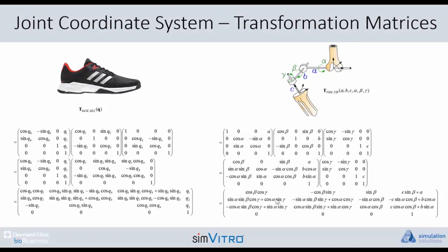So we have our roll, pitch, yaw reference frame, and see how the translations are here in that first matrix. And that basically means that we translate first, and then we apply all our rotations. And when we do that, the matrix gets multiplied at the end. We can easily extract those elements of the matrices to get our translations. If we look at the Grood-Suntay definition, the translations are spread out sequentially with the rotations.